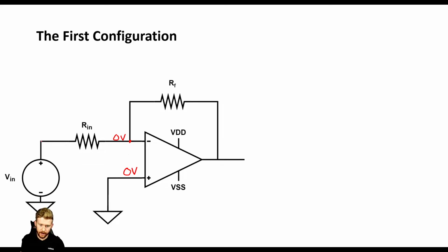So we know right here we have Vn because we're connected to Vn. So we know we have Vn here and 0 volts. Now, if we have a voltage drop across this resistor, what's going to start flowing? Current. That's exactly right. So we're going to start having current flowing through that resistor. So I'm going to go ahead and call this I1. Okay, and that's just going to help us later whenever we're doing a whole bunch of different math. It's going to help us keep our stuff straight. So I'm going to call this I1.